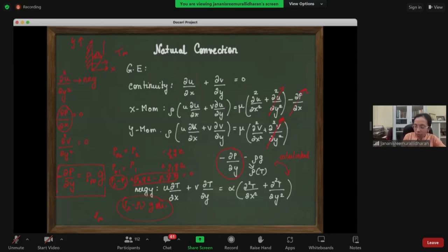So what I'm trying to do in this equation is to say that the pressure gradient, the way I am writing it, has a source term which is creating it, and I need that source term separately so that I can say density varies only with the source term. That's the way of writing the Boussinesq approximation. So I say the total delta P is driven by this, correct?